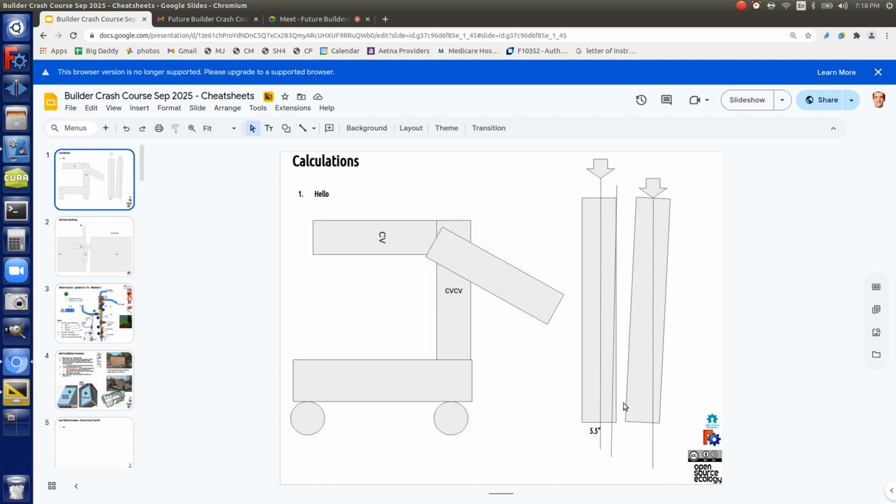So in the codes, they tell you the acceptable tolerance for vertical over 8 feet. I think that answer is like a quarter or even a half. Let's Google that because that's a critical thing. By code, on a wall, the inspector will fail you if it's not within so much of vertical. My guess is it's a quarter to a half.